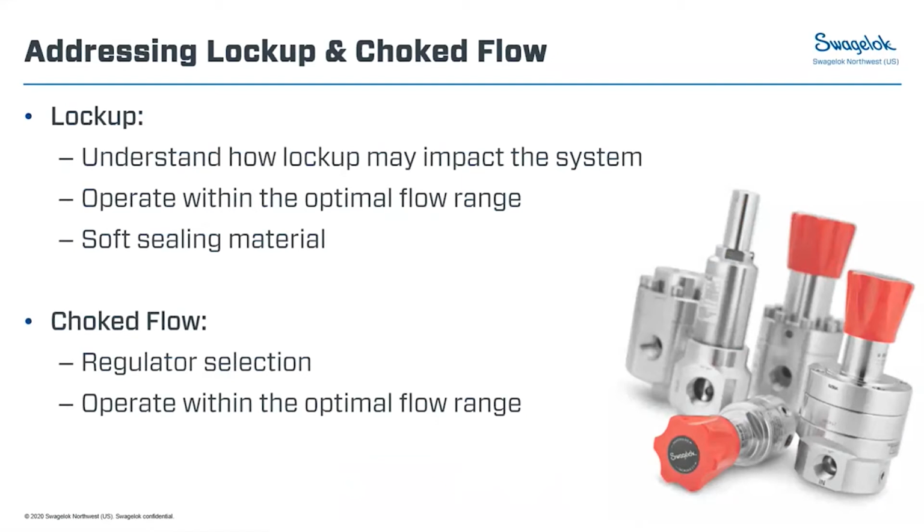This is for a few different reasons, but it's certainly possible that that slight increase in pressure might be enough that there's something downstream that we want to protect from that. So you may want to go ahead and install the relief valve for that reason. There are some other reasons that we'll get into in the future around installing a relief valve downstream of a regulator, but it's pretty much always recommended to do so.